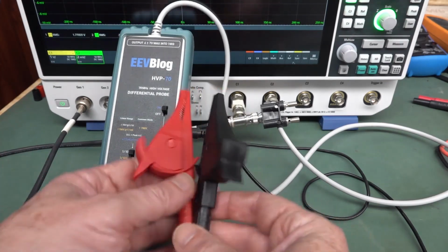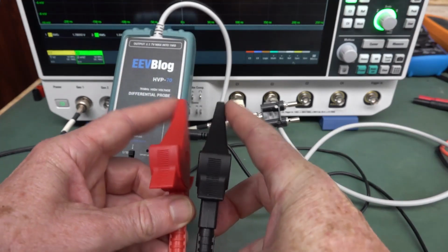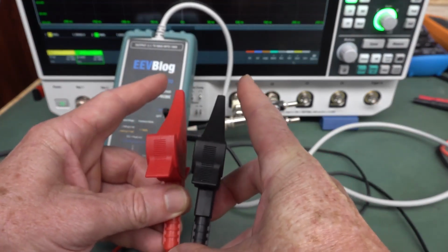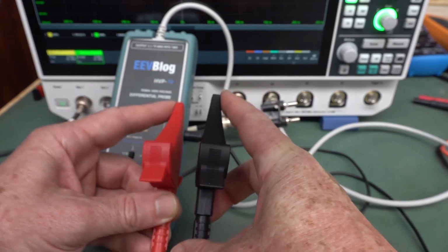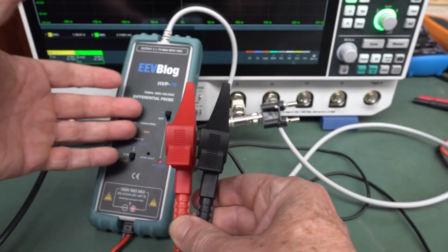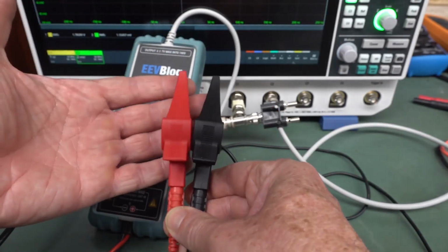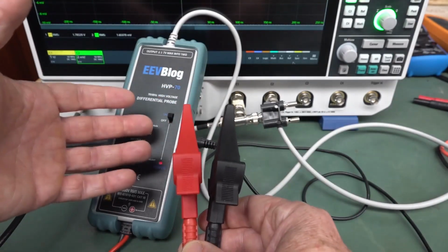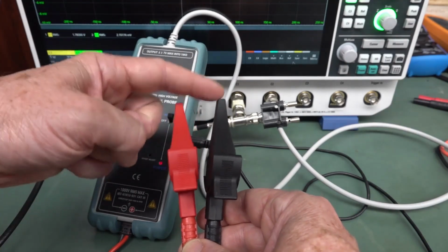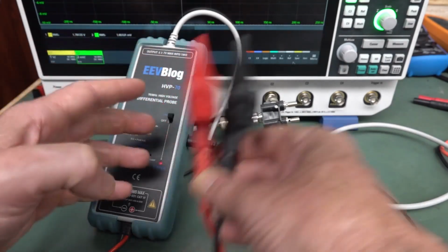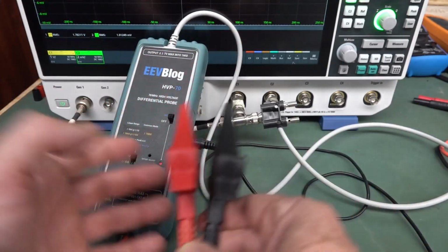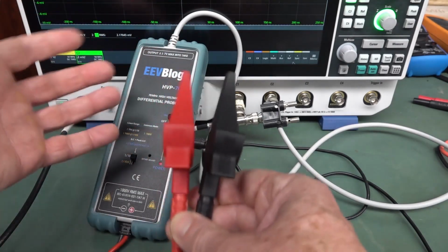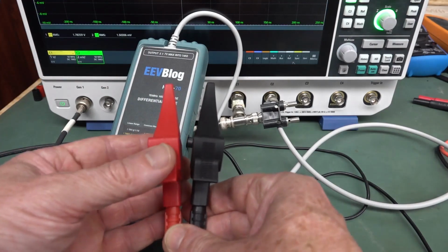Well, a differential amplifier measures the difference between two inputs here. There essentially is no ground reference. It is a differential signal, and a differential amplifier will have a gain of that differential signal. That's its job. If your differential amplifier has a gain of 10 and you put 1 volt differential across here, it doesn't matter where it is in the circuit, it's a differential voltage, doesn't matter about the ground reference, it'll multiply that by 10 and that's its differential gain.